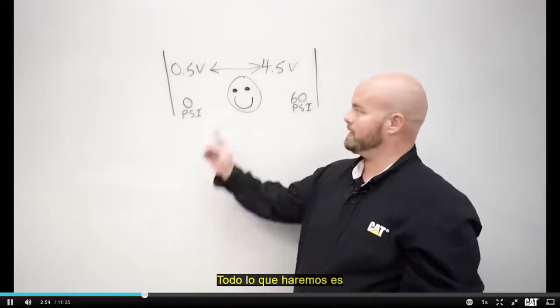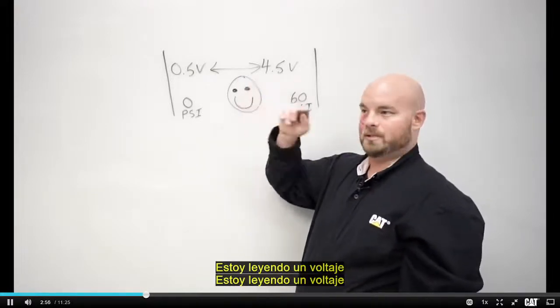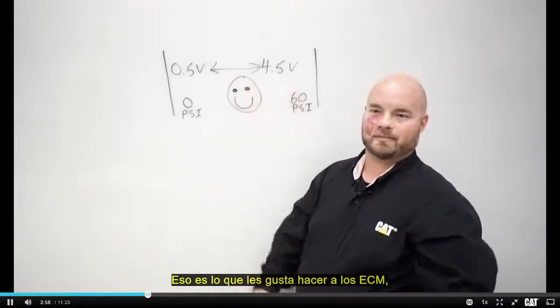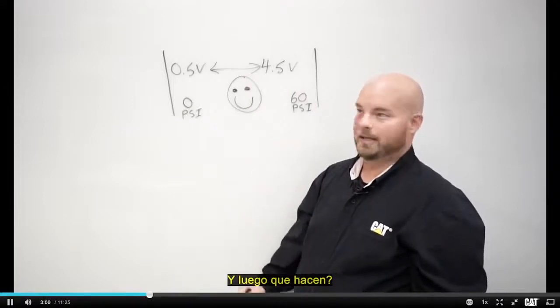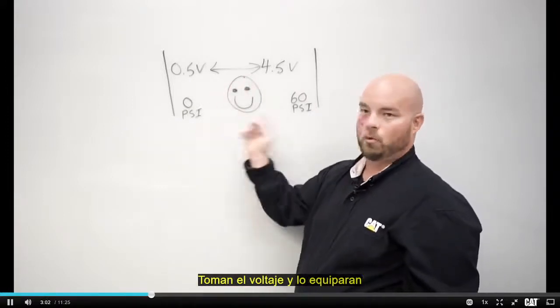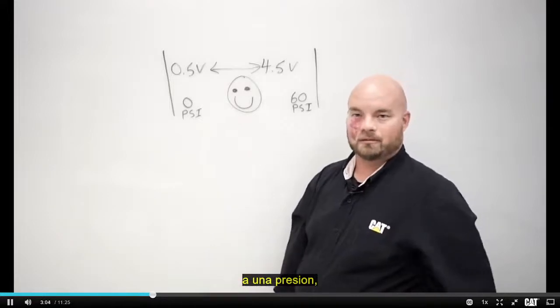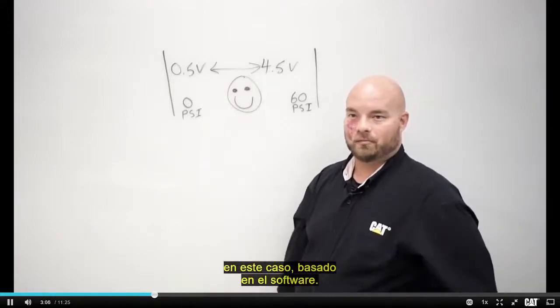All he's going to do is say, I'm reading a voltage, I'm reading a voltage, I'm reading a voltage. That's what ECMs like to do. They like to read voltages. And then they take the voltage and equate it to a pressure, in this case based on the software.